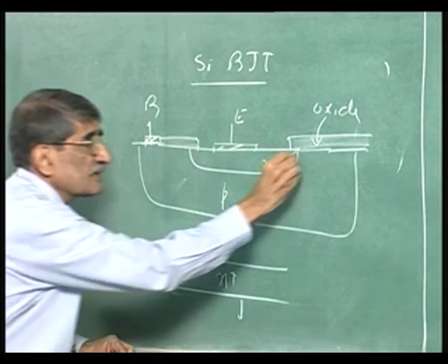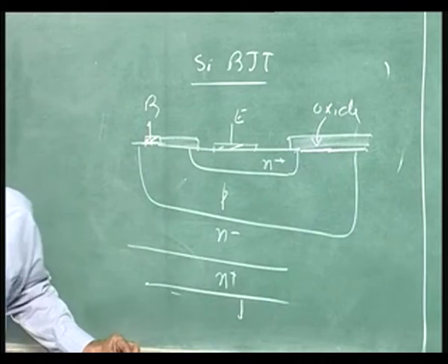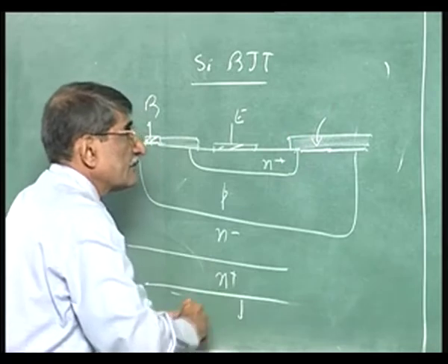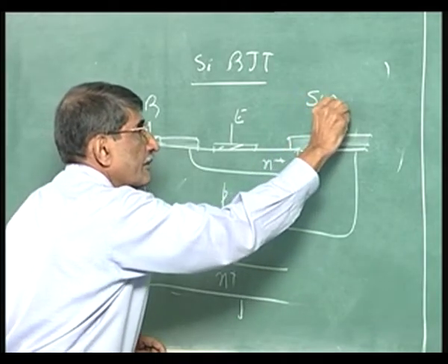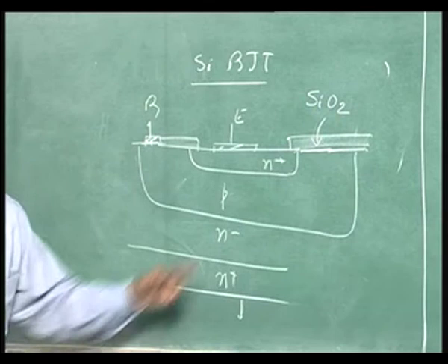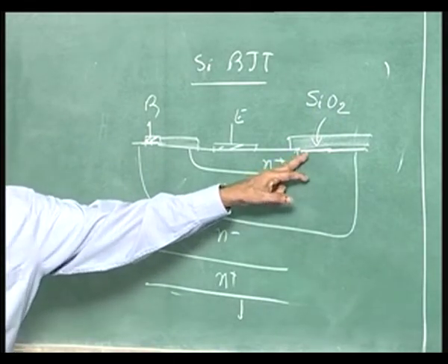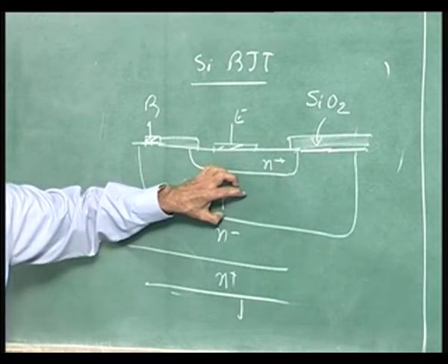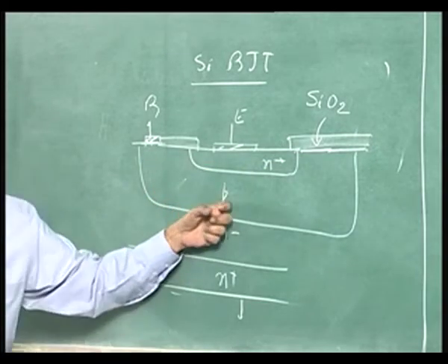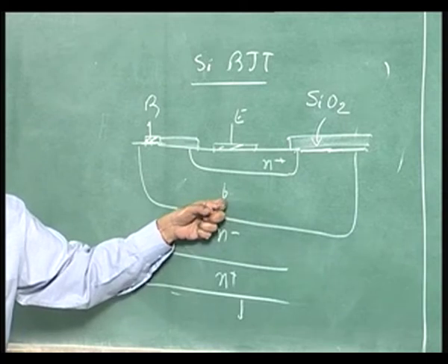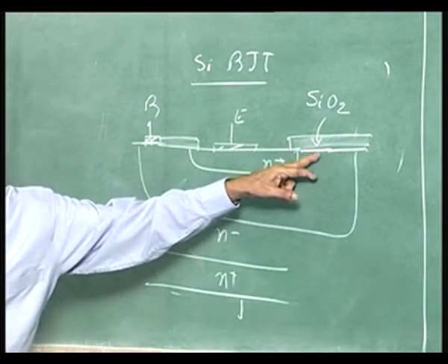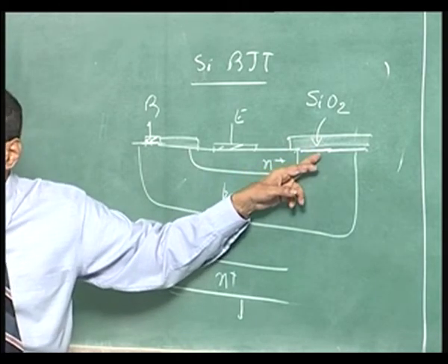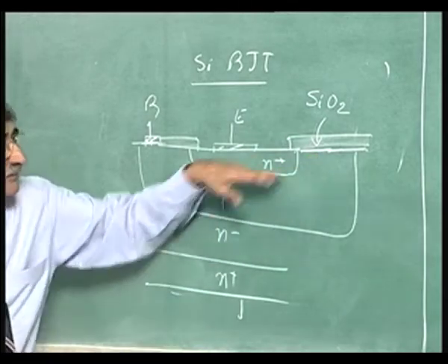So, this surface here has a protective layer of oxide. Okay. So, that is silicon dioxide, good thermal oxide. So, the recombination velocity, what we talked of last time, in the sense just like in the case of bulk, where stored charge divided by lifetime is the recombination current, okay, you have got recombination current into the surface. The current or the electrons are lost to the surface due to transport of the electrons from here to here.